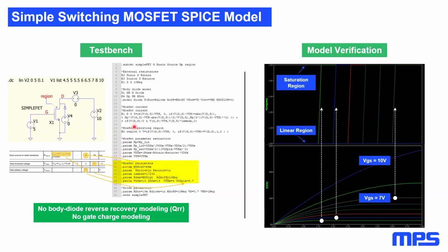Inverting the theoretical expressions, the Kp parameter can be extracted by identifying some key quantities from the vendor's datasheet, which are the RDS on, the VGS drive voltage and current at which the RDS on is defined, and the threshold VGS voltage.